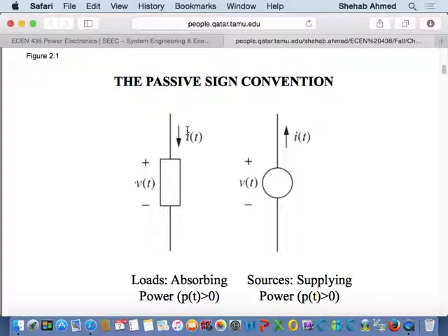When the vehicle is braking, you can use that brake. You can do something called regenerative braking. So it's electrical braking instead of mechanical braking with pads. You do what is called regenerative braking. In regenerative braking, the motor is acting as a generator, and it's feeding power into the batteries, right?